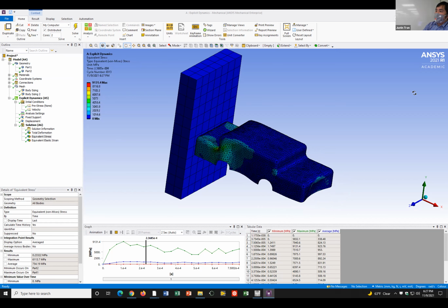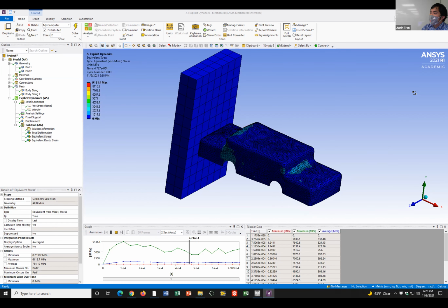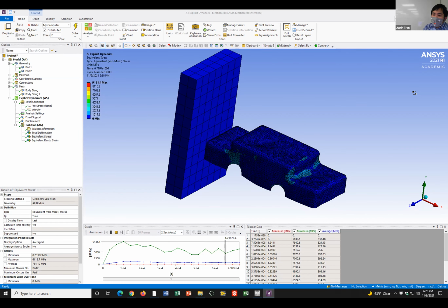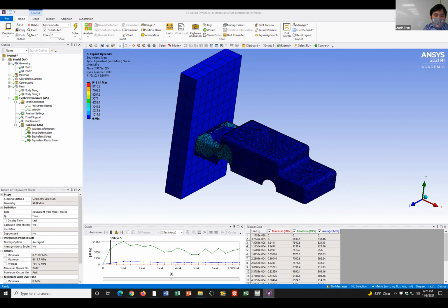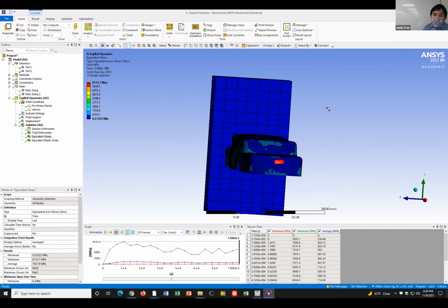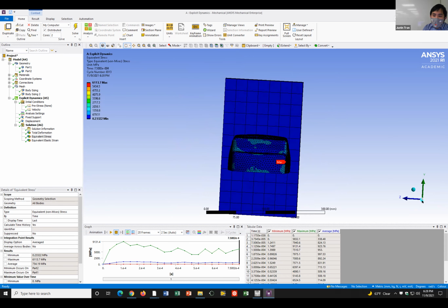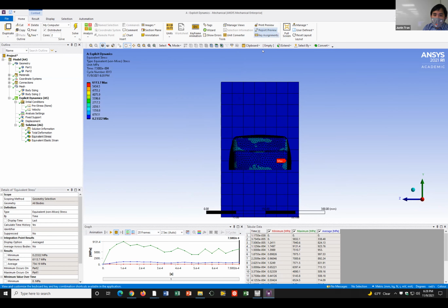Basically, you can cut your simulation time to about half by using symmetry. And actually, you can apply symmetry for this problem here. If you look at it from this perspective, if I drew a line right down the middle here, imagine I drew the line better, the car on the left of the line and the right of the line is exactly the same.